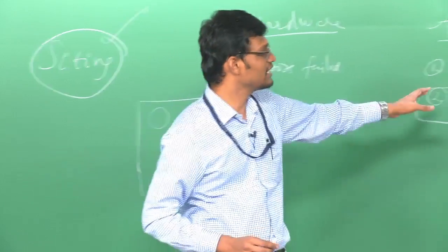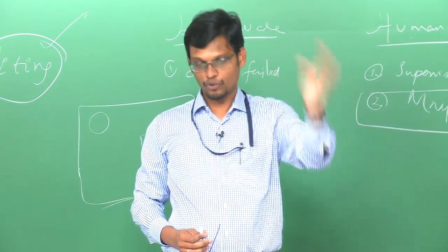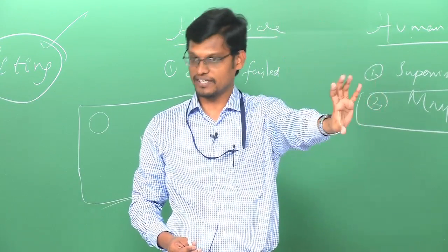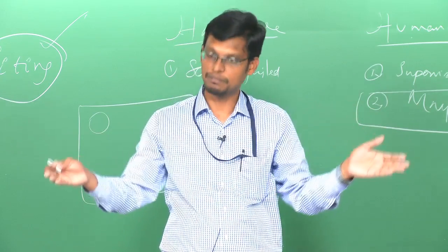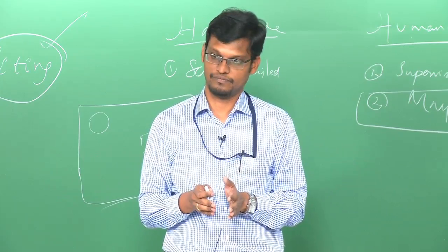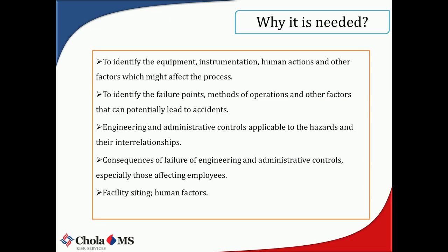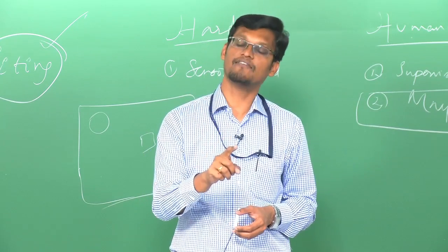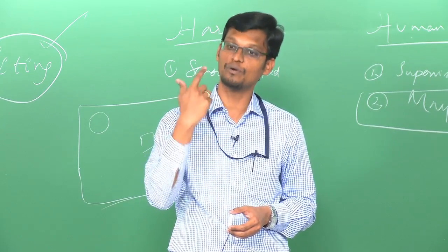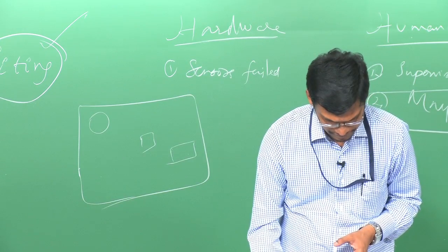Okay. So, assuming one person is looking after 3 panels and one is going for startup, the one going for startup has to be monitored continuously, right. So, if one person is designated to manage multiple things, then you will have a problem. That is where human factors come in, the last line. Human factors in process safety is more from this perspective: how an operator at field level responds to a particular emergency, in terms of how he has understood and is handling it.